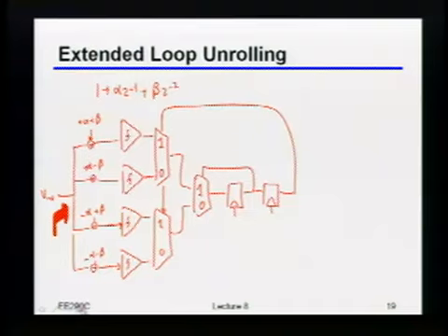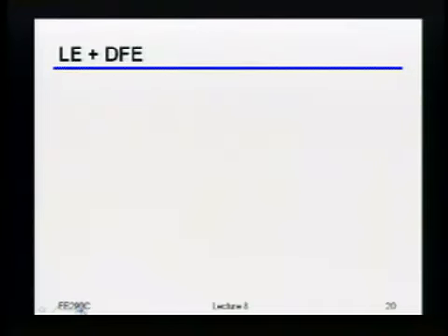Okay, so there were just a few practical issues that I wanted to briefly mention. This one I think we mentioned a little bit last time already, but just to make sure it's clear to everybody. As hopefully you saw from the homework, a lot of times you'll actually combine a linear equalizer with the DFE. And in some senses, sometimes you'll even just build the DFE to make life easier in terms of actually doing the linear equalization.